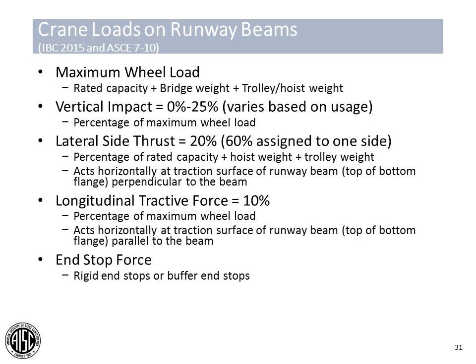They may need to be tightened down or reduced to the criteria set forth for the crane systems as well. Excessive deflection in crane systems has led to a substantial number of crane problems or crane failures. It's a very big serviceability issue for the cranes themselves. So you should consider the reduction in allowable deflection of the overall superstructure based on this crane system. I would say anything supporting the crane should meet the deflection criteria set forth by CMAA.